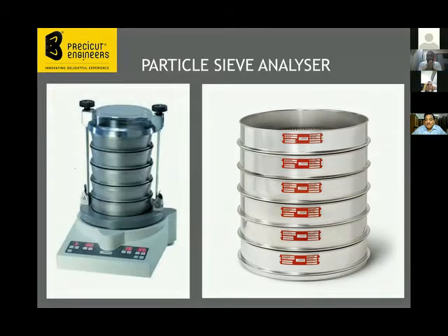So say for 0.6 to 0.7 mm shot size, there will be a particular set of sieve sizes that are mentioned in the standard. Now if the shot size changes, say we go to a higher shot size 0.8 to 0.9, in that case again the sizes of these sieves will change. Now what the standards say is you take roughly a sample of 100 grams by weight, and you put it in this analyzer.